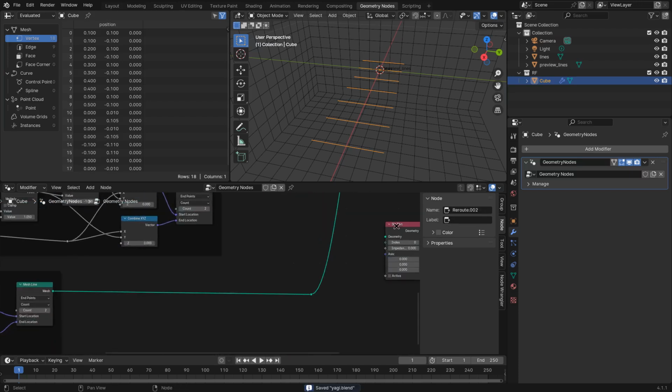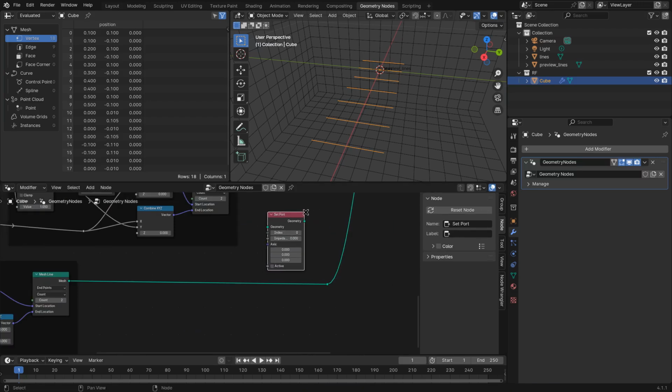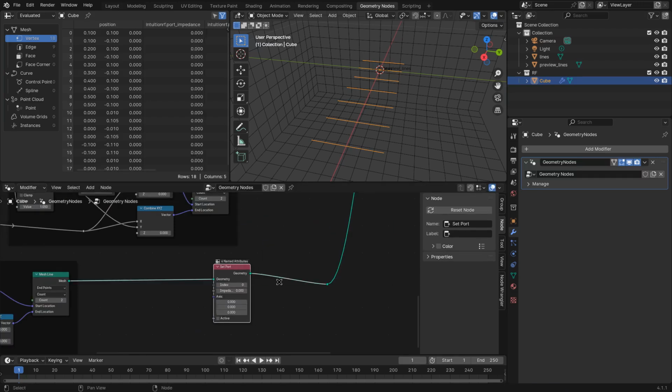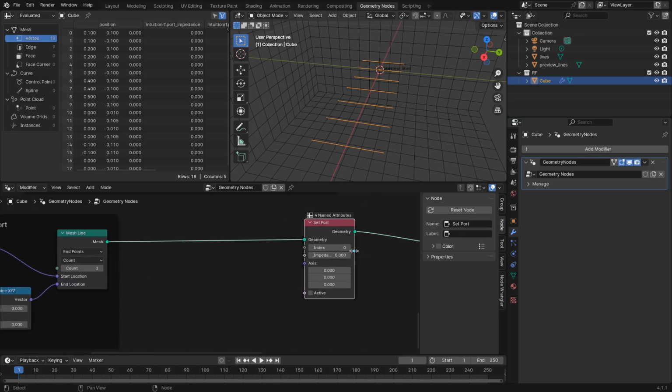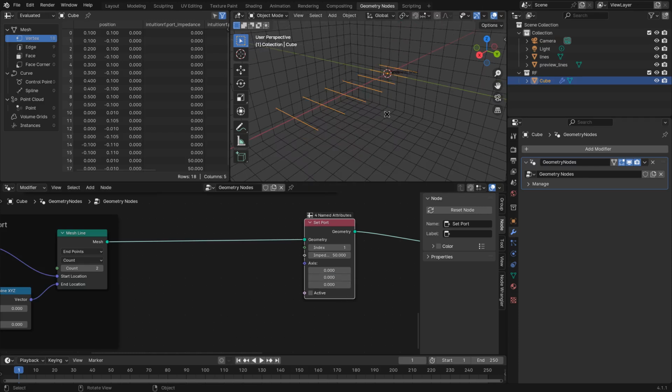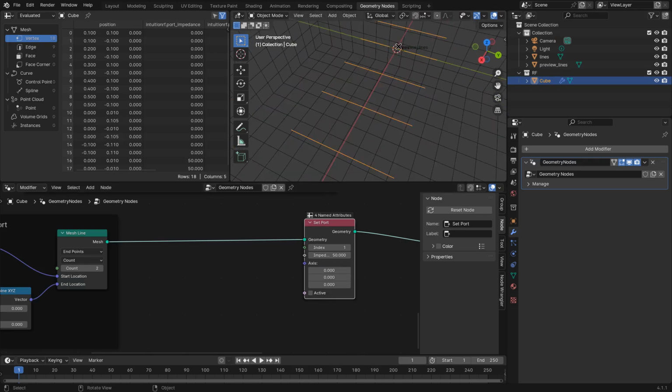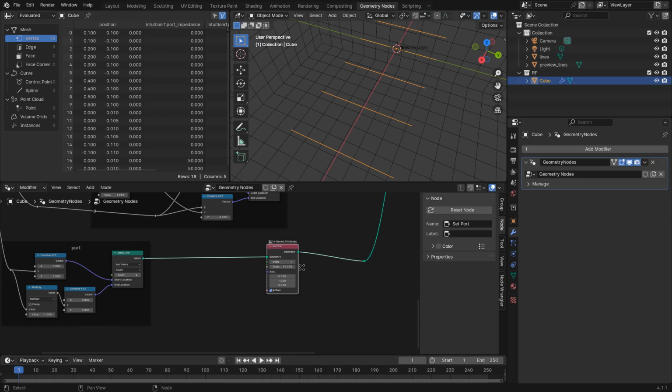So let's use that port node, and let's put it here. And now we can define what our port does. So it needs to have a non-zero index. So let's go with index 1, impedance of 50 ohms. And we need to define an axis. Now you can't define an arbitrary vector, it will be snapped to the nearest axis. So in this case it's on the y-axis, so let's put 1 here, and then it's also going to be an active port. Okay.